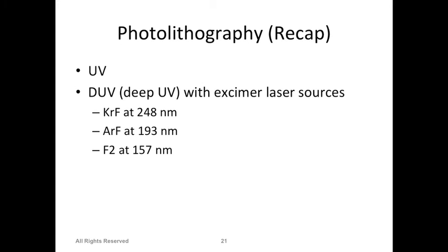And then there was another one, phase shifting, right? So we are shifting the phases between any two enclosed windows, right? In that way the exposure will be more uniform. You will have more exposure and less exposure because of the cancellation of the phases at the boundary. Phase shifters are commonly used in masks. Those are basically expensive masks where you have a phase shifter layer. A phase shifter is just a small layer of another material which slows down the light passing through it, which shifts the phase. So you end up getting a better resolution by doing it.